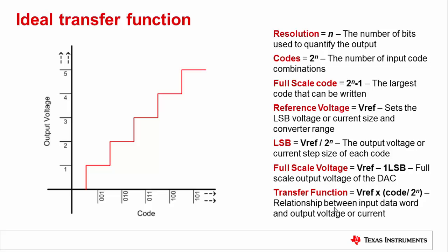The reference voltage is arguably the most important piece of any data converter system. Any noise on the reference will translate to noise on the DAC output. Additionally, the reference voltage defines the output range of a DAC and is used in determining the LSB weight, one of the most important items to understand about a data converter.